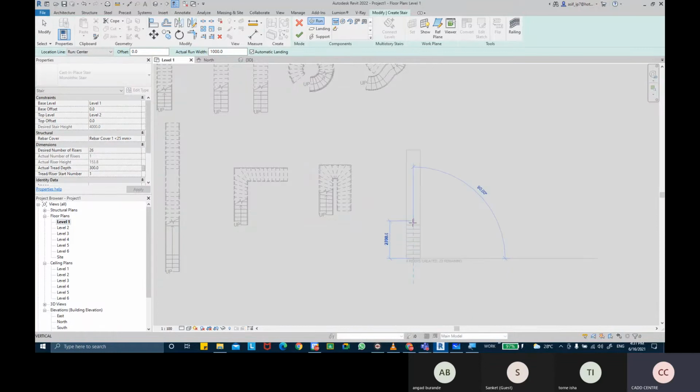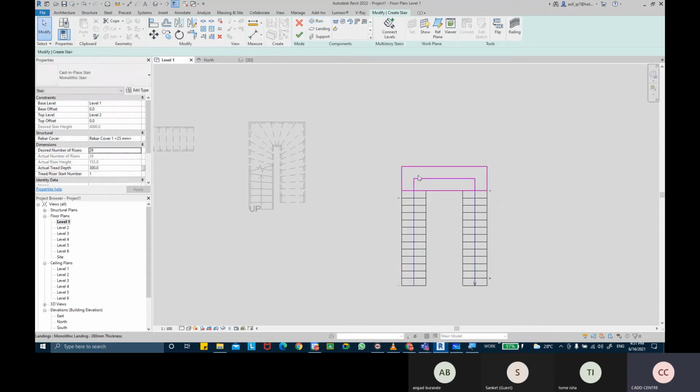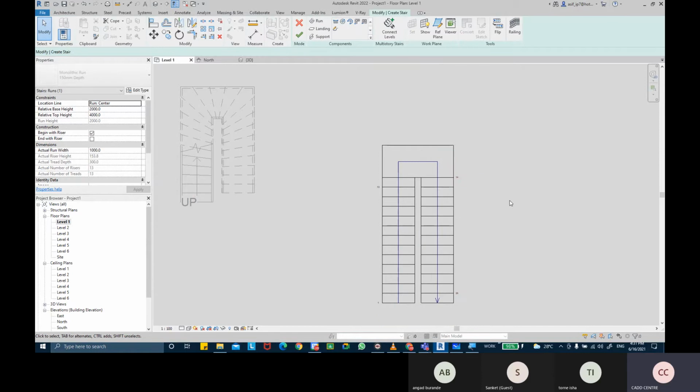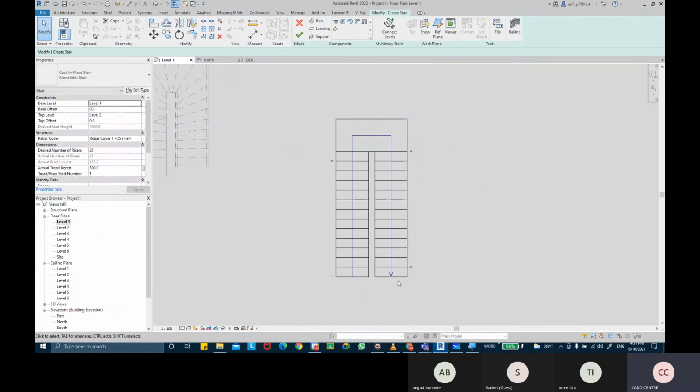So I'm going to drag and make sure that I only create half of it. You can see 13 risers created, 13 are remaining. I'm going to stop over here. We're going to start from this direction again and go to the opposite side this way. It goes like that. You can see this becomes my mid landing, and then this goes up again. You can select them and drag this a little bit this way. So yeah, the staircase revolving all the way around.